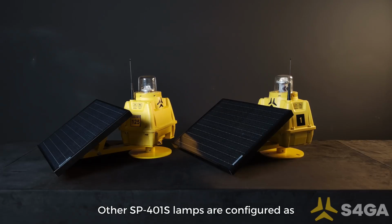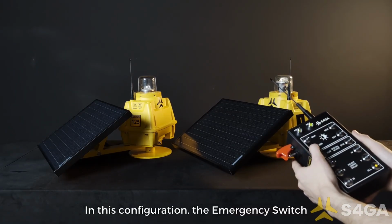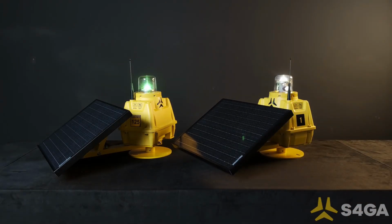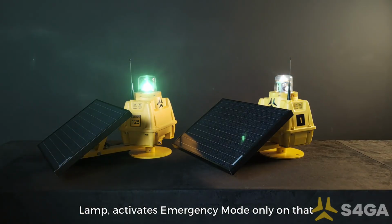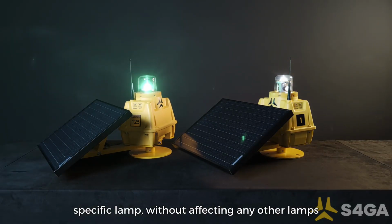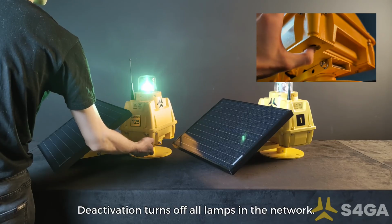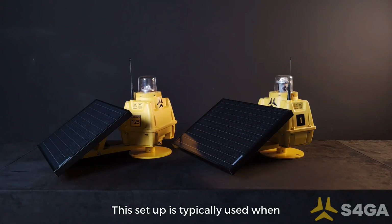Other SP-401S lamps are configured as non-emergency lamps. In this configuration, the emergency switch works locally only. Pressing the emergency switch on a non-emergency lamp activates emergency mode only on that specific lamp, without affecting any other lamps in the same radio network. Deactivation turns off all lamps in the network. This setup is typically used when individual, isolated control is required.